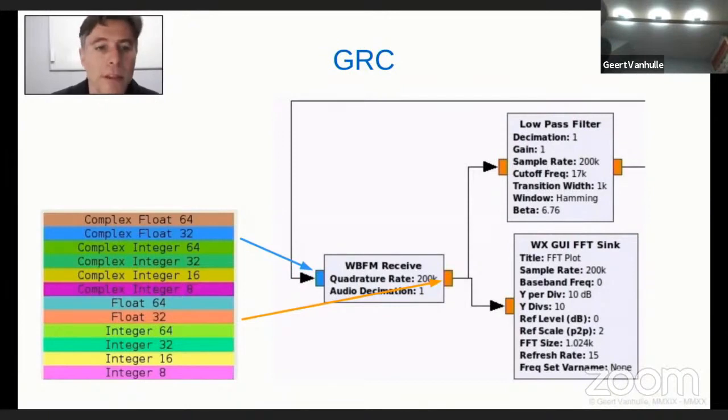So no longer a complex signal, a normal sample series, but of 32-bit float values. Now the WB-FM is a wideband FM demodulator. It's a quadrature demodulator. How it works inside would lead us too far. It's just software, a mathematical representation. Again, just like we discussed with some other parts before, mathematically, you can also demodulate from this 200 kilohertz baseband the analog output signal in a digital sample representation form, of course.